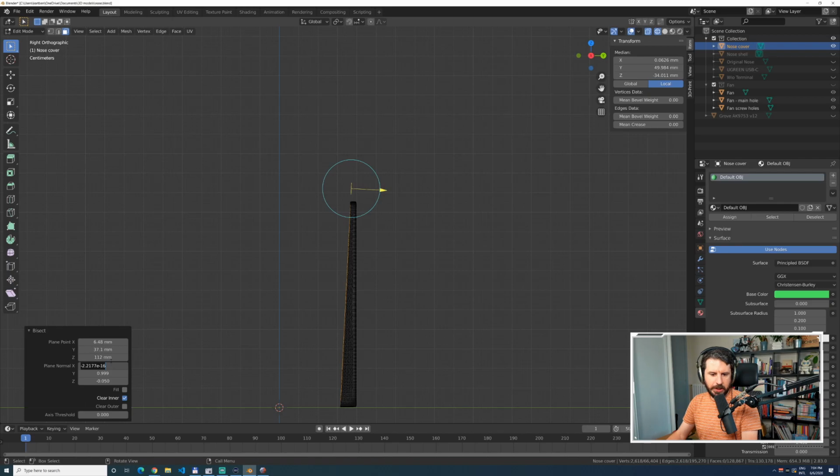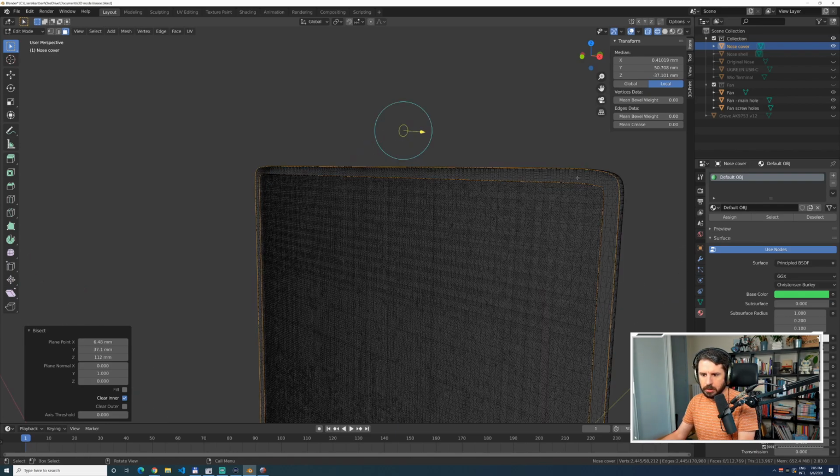I want it to be vertical, and I forgot to tick the box for Blender to fill the gaps. When it cuts, I actually want the faces that are part of the split to be filled. I hope I won't do the same mistake. Right now there's nothing here, which is really bad because strictly speaking it's not even 3D printable. I want this. There we go. And that makes more sense.